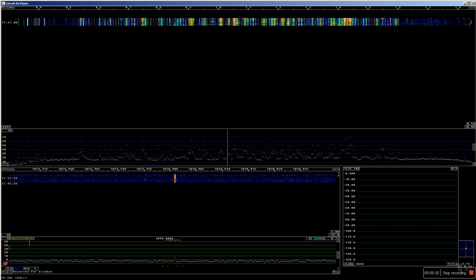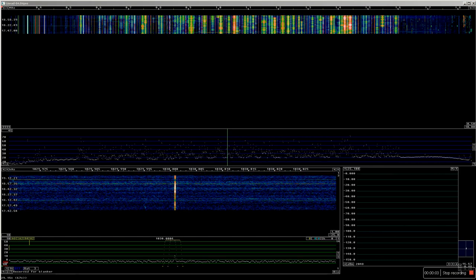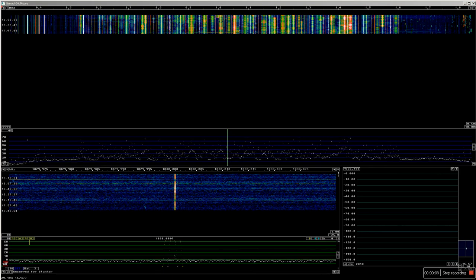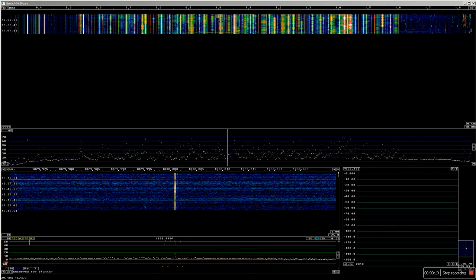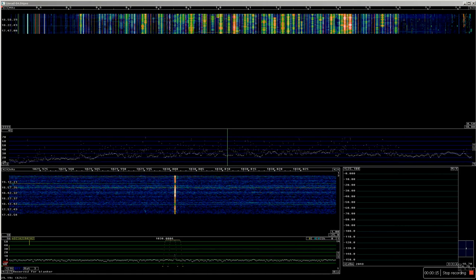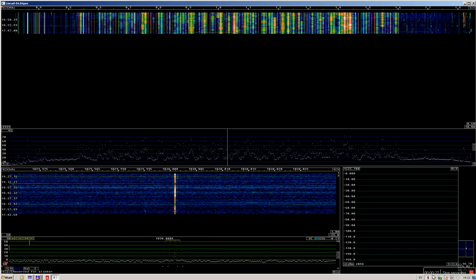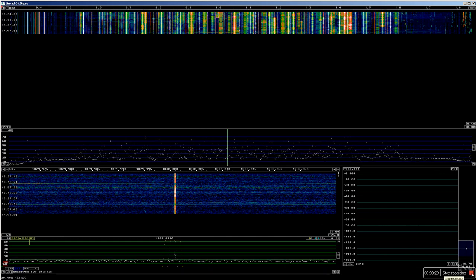So I leave this running for a while and then come back. And since I didn't have memory to increase the resolution as much as I had thought, the waterfall is running much too fast. So I changed that from 10 to, let's say, 50 to get it 5 times slower. And then I will repeat and come back when it has shown a reasonably long waterfall.